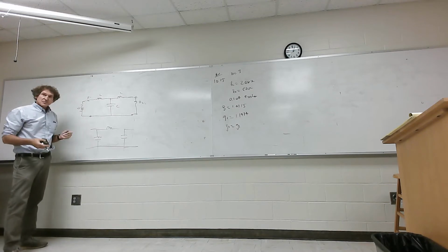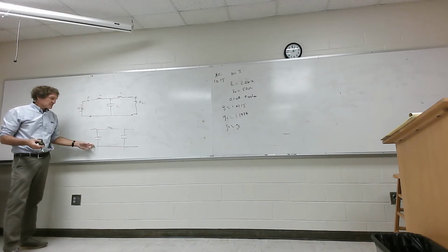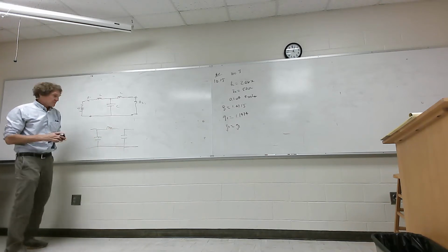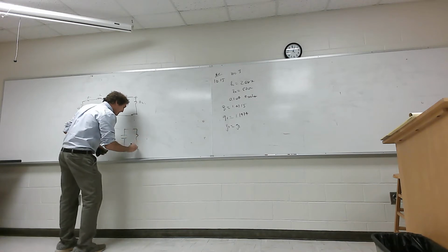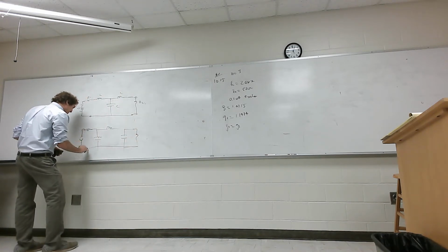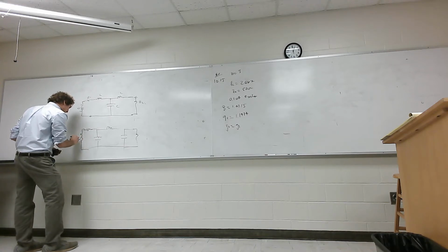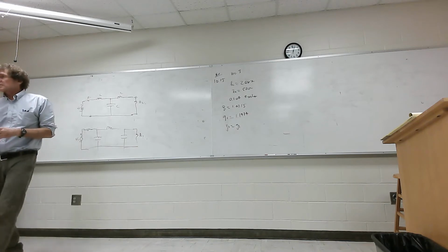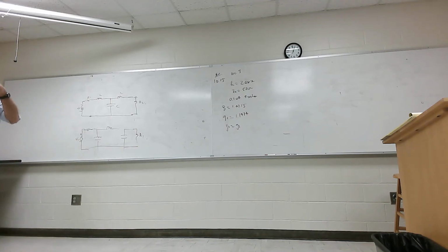And if you look at this one, same deal. The capacitors at high frequency will short, so this will look like a short. This will be an infinite impedance, that'll be a short, so put a load on here. You can see that this too is going to be a low pass filter. Y'all with me? Now we're going to start with low pass and we'll transform it into high pass, but right now we're going to get the values for both of these.